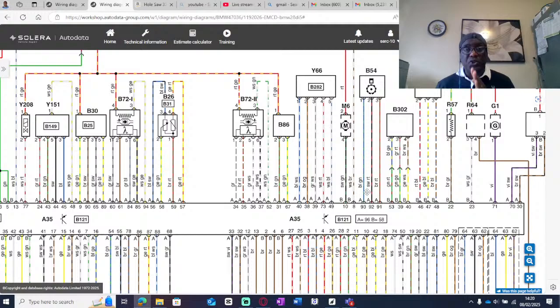It is important when you are testing something to know where your signal is coming from. Usually people think the signal is coming from the ECU. No, it is actually coming from the sensor itself. So now we're doing well. I am not going to be long. I just want to show you the basics so that we start from there.